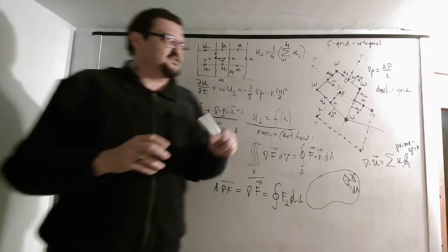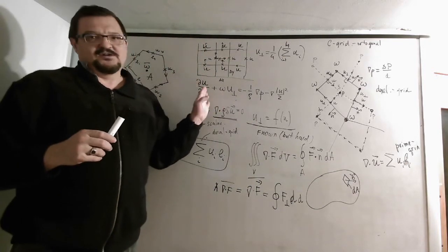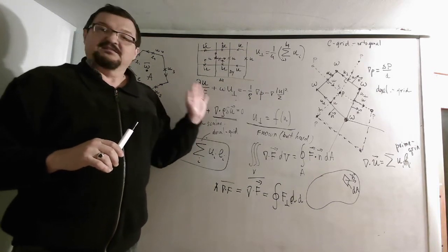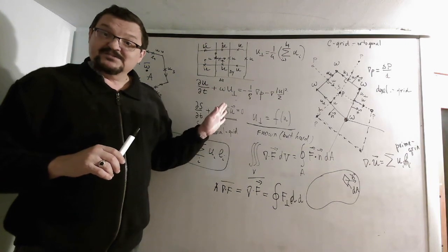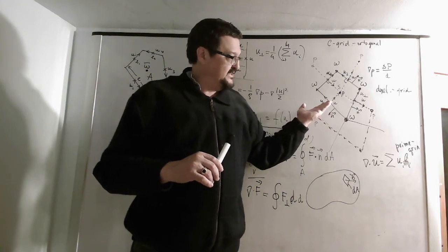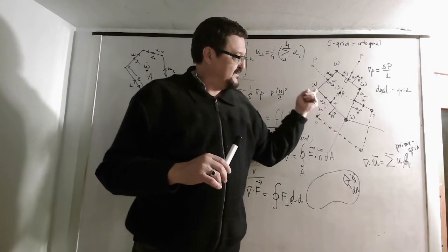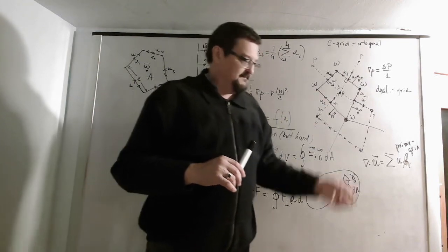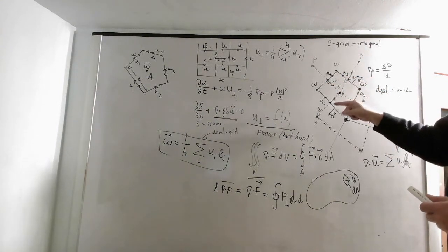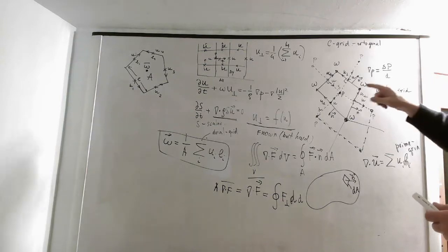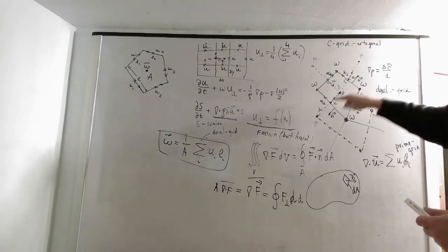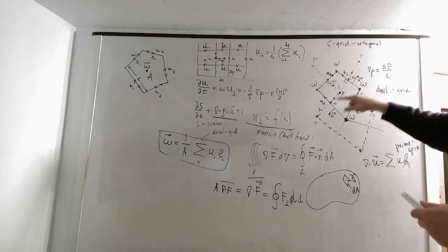So I'm just talking about the conceptual idea of this particular way of doing the finite volume method. And again, the beauty of it is that no coordinate system is involved at all. All you have to do is define the direction of your main wind vector that is perpendicular to the edge of your grid element, and also, in order for this method to work, your prime grid edges should be perpendicular to your dual grid edges,